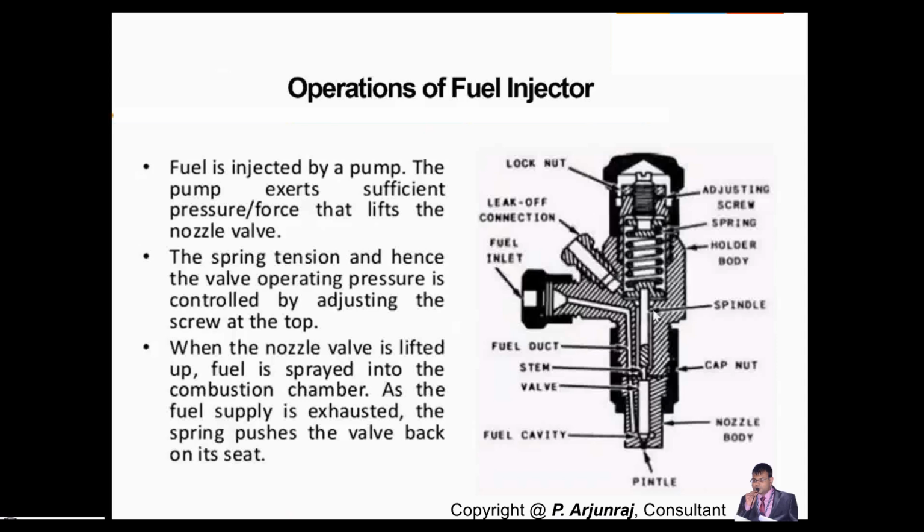Okay. So fuel is injected by a pump. Whatever fuel is there in the tank gets lifted up. The fuel pump is also called a transfer pump or lift pump. The pump will exert sufficient pressure and force that lifts the nozzle valve, and you have the valve here. Basically, this is called a nozzle valve. This nozzle valve gets lifted when the pressure is higher.